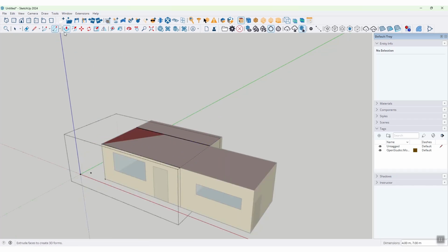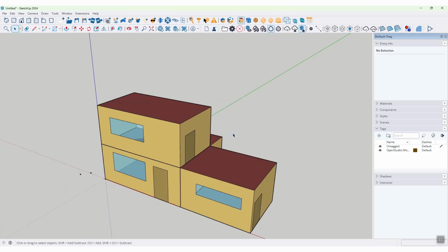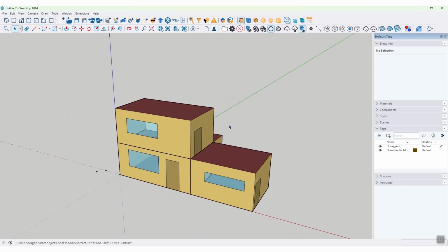An important point to keep in mind is that even though the spaces are visually placed next to each other, OpenStudio does not always detect the adjacency between the two surfaces automatically at the beginning. The wall between two spaces may still be recognized as an exterior wall, or outdoors, while it should actually be defined as a surface adjacent to another space.